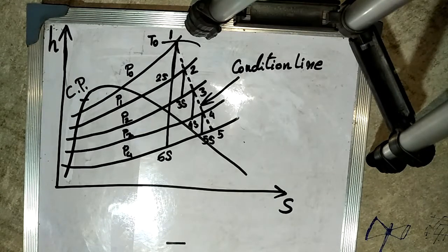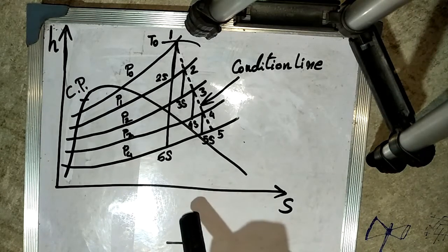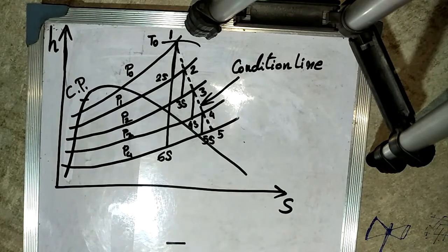As shown in this figure, it shows the expansion in a 4-stage turbine taking into account the effects of reheat. From this we can draw the following conclusions. First, the reheat takes place with the increase in entropy. Second, the reheat in a given stage is available to do work in the succeeding stage, except the last stage where the reheat is a loss.